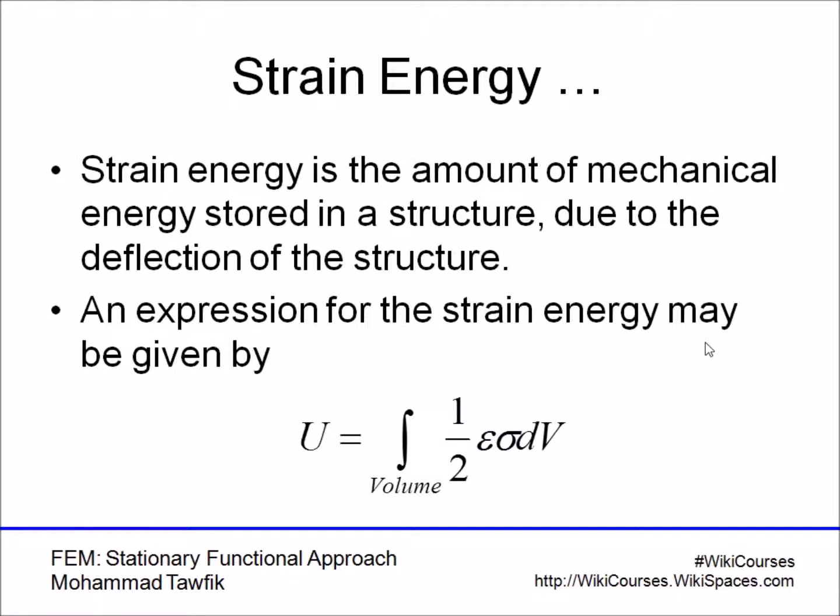Now, as we introduce the strain energy and the total energy, let's just remind ourselves of the expression for the strain energy. The strain energy of an elastic structure would be the integration over the volume of the structure of half the stress times the strain. So this would be the general definition of the strain energy stored in any given elastic structure.